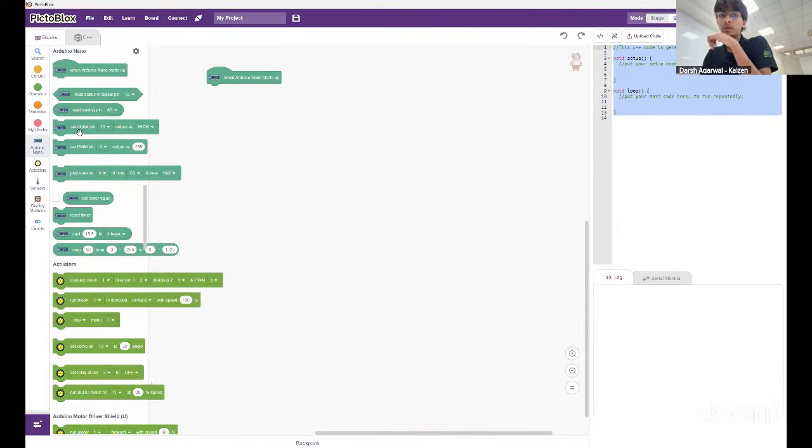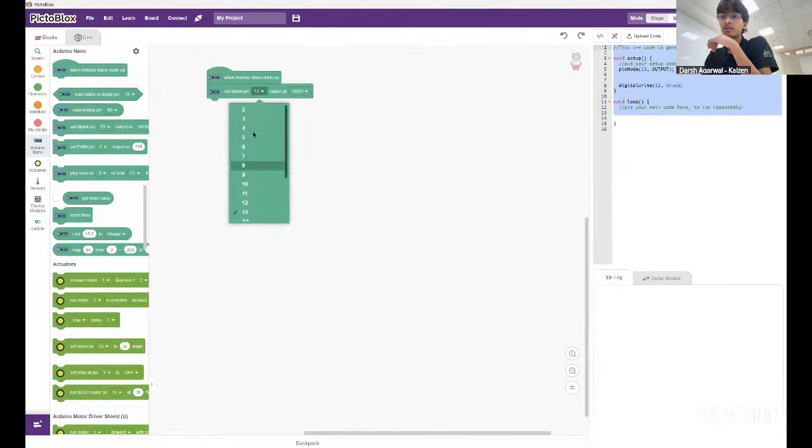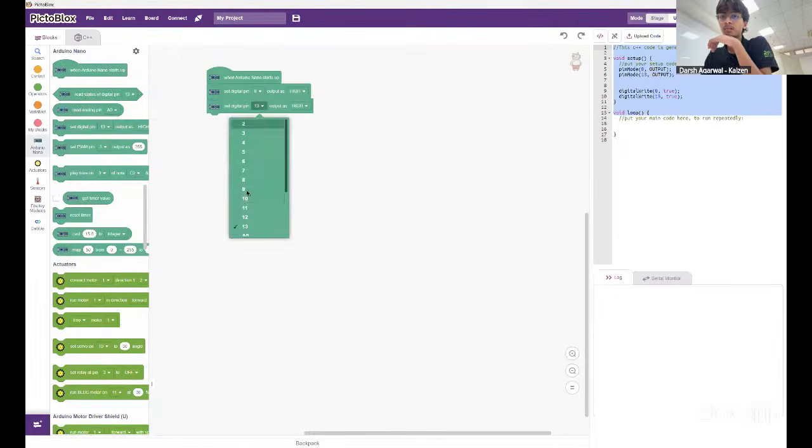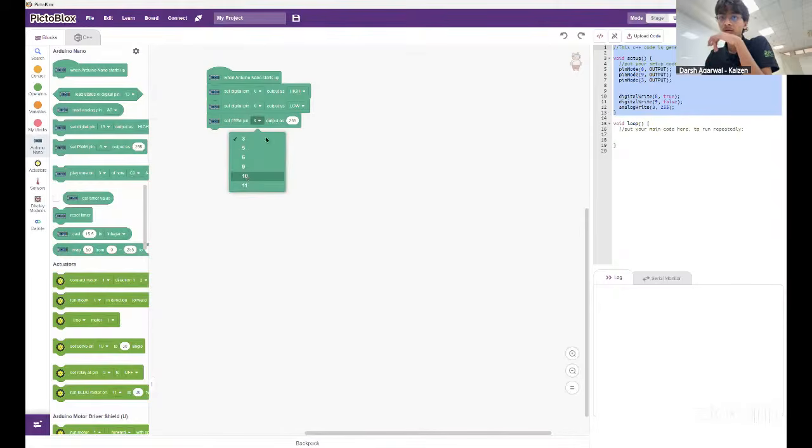So in my Arduino board that I have right now, I have the pin configuration set so that pin 8 will output high, and pin number 9 will output low, and I have one PWM pin, which is number 10, or sorry, number 11, which will output 200 instead of 255, right? So on its own, as soon as I upload the code from here, it's going to start running those motors, because I'm essentially sending high and low signals to each of the pins, right?